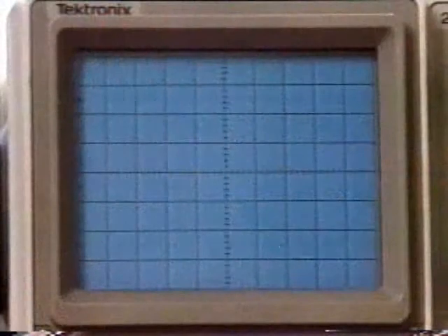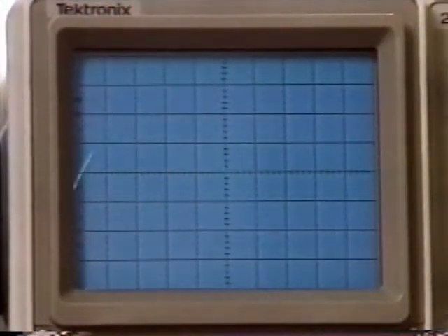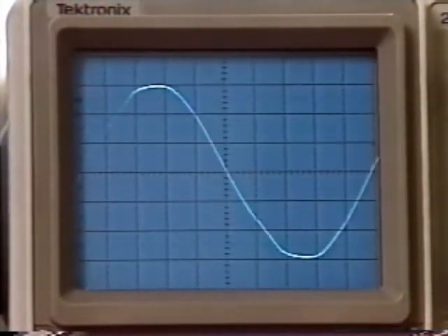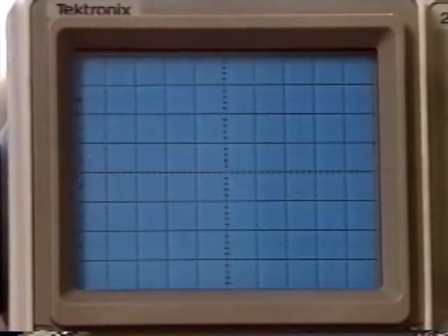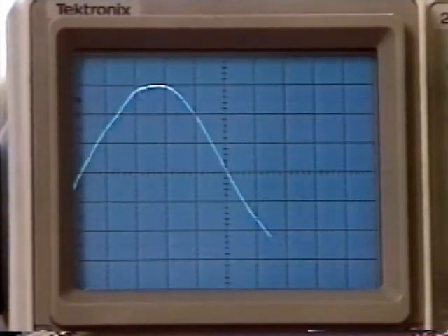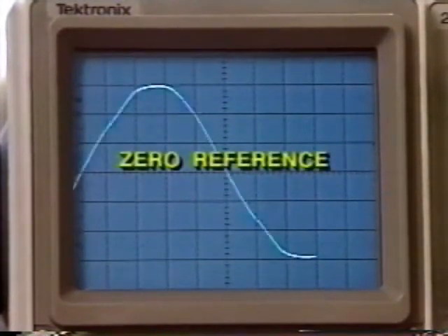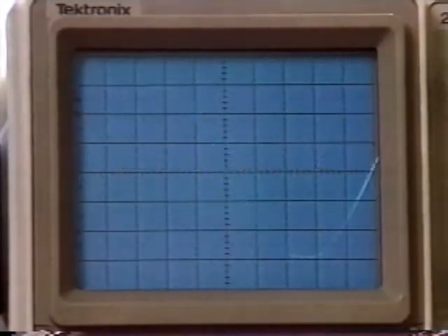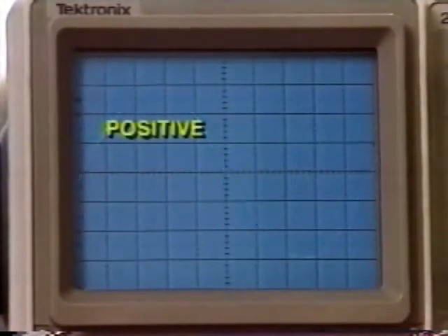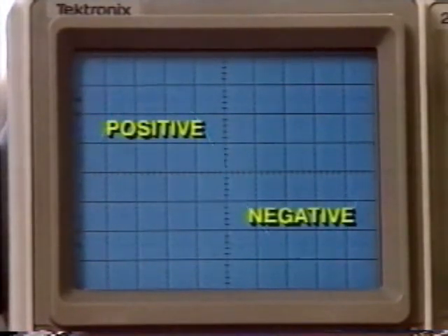One of the most dramatic applications of the diode is within the context of an AC circuit. Remember that in an AC circuit, the direction of current flow changes at some regular interval. Another way of describing this change in direction is to say that the polarity of the source reverses every half cycle, which you can see on this oscilloscope. The midpoint between the upper and lower peaks of this waveform is the zero reference. Current flows in one direction through the circuit during the positive half cycle, and then flows in the opposite direction during the negative half cycle.